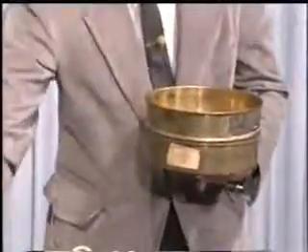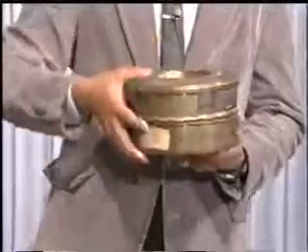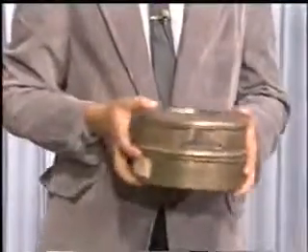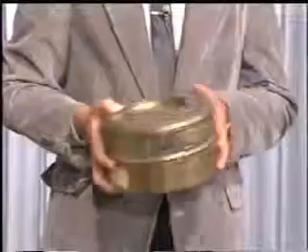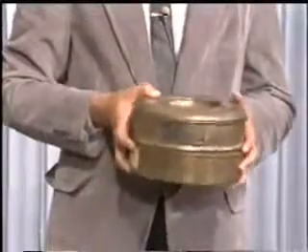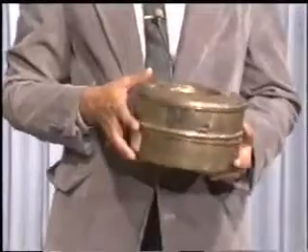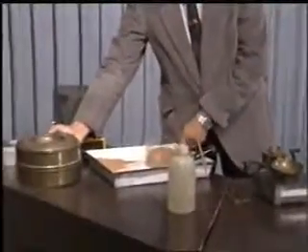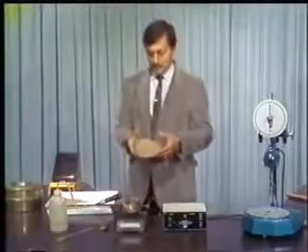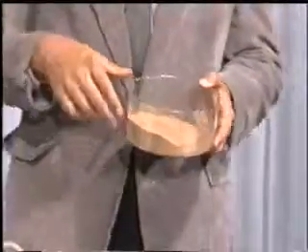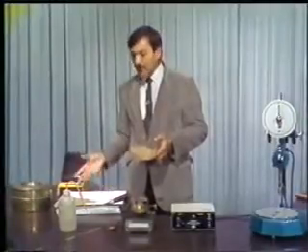It is then covered with the lid, and then it is shaken for a few minutes so that some sample will pass through the sieve. The sample passing through the sieve is collected. So this is the sample which we have obtained after sieving. Now about 150 grams of the sample is required for preparation of the specimen.